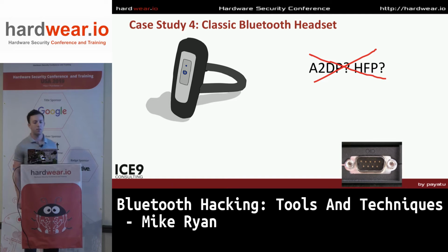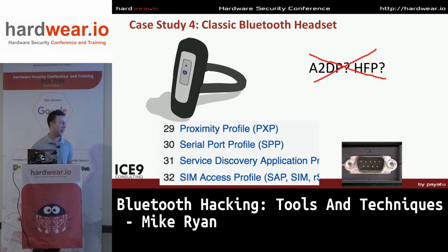There is another custom serial port. Why is there another custom serial port? Well, reasons. They're actually somewhat pretty good in this case. This is a classic Bluetooth device. This is not a BLE device, and that helps us to a certain extent because there's already a profile in classic Bluetooth for speaking as a serial port, the serial port profile.